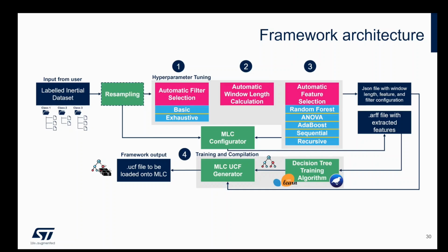So once these three pieces are done, then this ARFF file will be generated from this. You will process this through and generate a decision tree out of this whole logic. And finally, the decision tree that is generated out of the tool, either this tool or you could use your own favorite tool to generate the decision tree, whether it's Weka, RapidMiner, MATLAB, whatever it may be. Or you could do all of that in MEMS Studio. Ultimately, you will produce the decision tree that can be embedded inside the sensor.